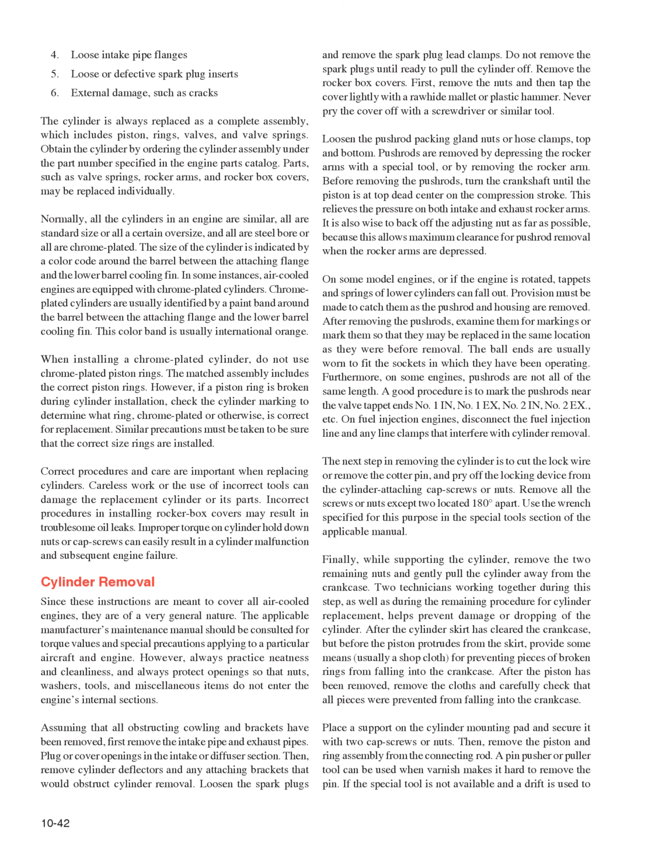Correct procedures and care are important when replacing cylinders. Careless work or the use of incorrect tools can damage the replacement cylinder or its parts. Incorrect procedures in installing rocker box covers may result in troublesome oil leaks. Improper torque on cylinder hold-down nuts or cap screws can easily result in a cylinder malfunction and subsequent engine failure.